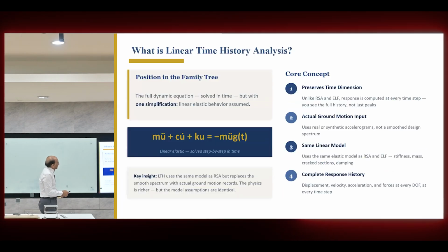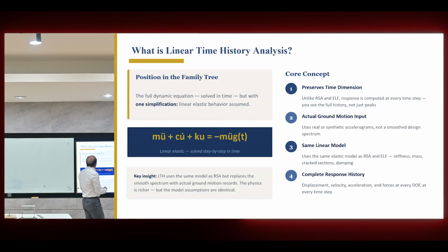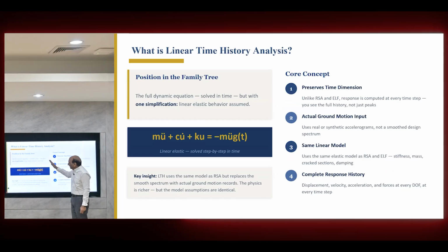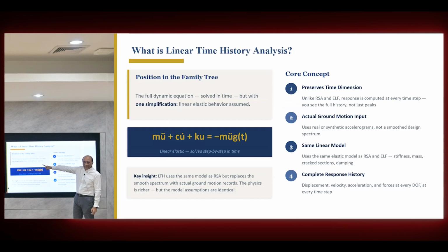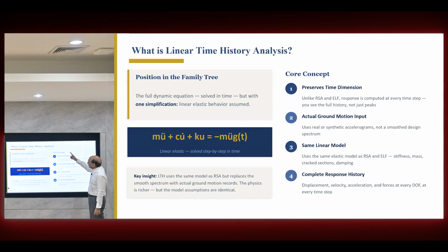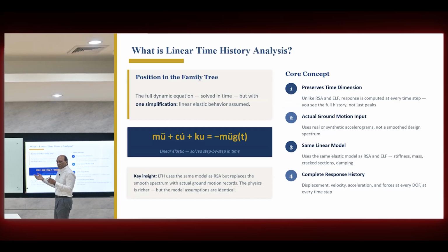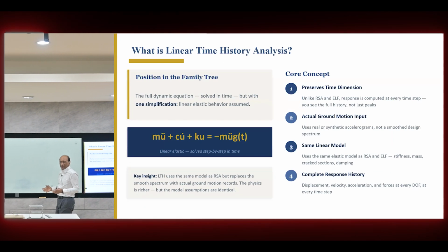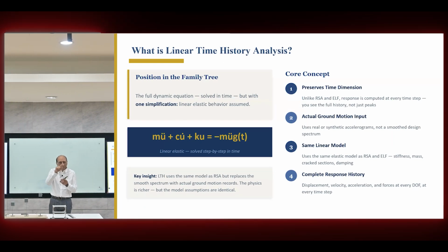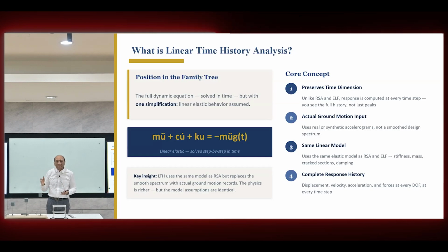So basically, this is the full dynamic analysis solved in time, but with one simplification: it remains linear. Damage and nonlinearity is not considered. So we take this equation, linear elastic, and the core concept is that it preserves the time dimension. In the response spectrum, time is not considered. So you are taking the response at any time and just saying they are all the same.